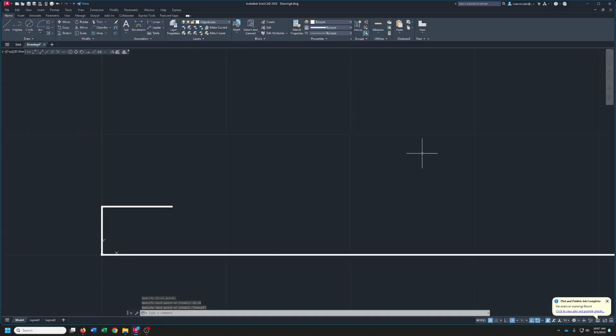Now, this is where we're going to start using construction lines a lot, because we got to make some markers and stuff like that. So I'm going to go back to my construction line, and I'm going to just draw my line up. It doesn't matter how long. About that far will work. And we're going to offset that line to find the center of our first circle. So we got to come over 2.5. We're going to offset 2.5 in that direction.